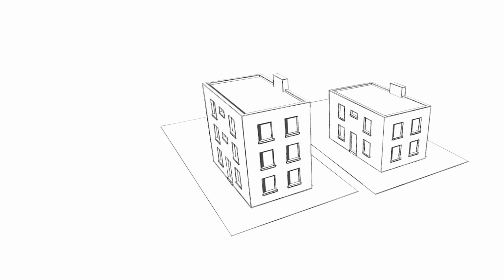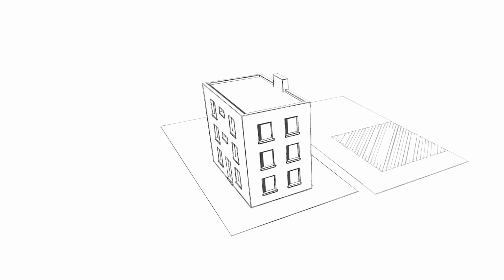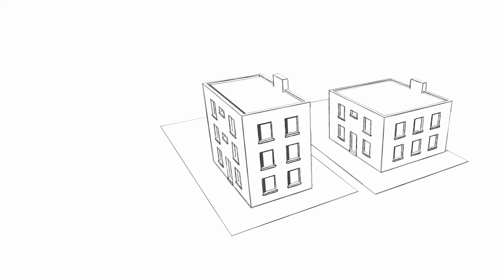Usually not all, but only a few of these specifications are made. This leaves an individual scope within the legal restrictions for building on a plot. For example, these two buildings have the same Grundflächenzahl, but a different Geschossflächenzahl and number of stories. These two buildings, on the other hand, have the same Geschossflächenzahl, but a different Grundflächenzahl and number of floors.